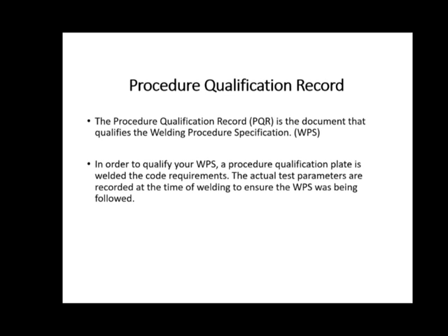They're going to send you back a stack of results for your mechanical testing, tensiles, bends, whatever, and then you're going to take that and you're going to write a PQR. When you're done writing the PQR, you're going to write a WPS. That's how the system works.